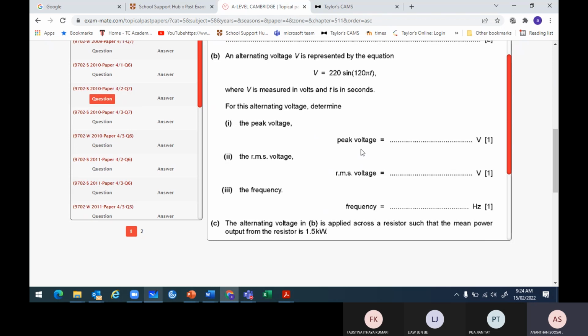But now with AC, another problem: which V to use? V RMS or V peak? Substitute the power as 1500. 1500 equals V squared over R. Which do we use? RMS. Use the RMS value because it's average power. If they just say power, use V RMS. If they say peak power, then use V peak.